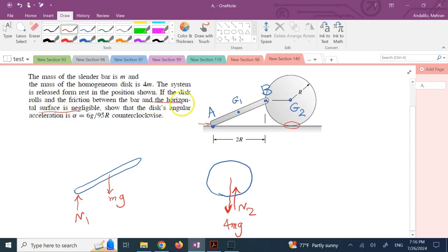The friction is negligible. But in here there is friction, and if you make a mistake about the direction of that static friction, that is not going to be good. That is because the friction only has one direction. It opposes the potential motion. It never helps with the potential motion. So if you do it the other way, you have ruined the solution.